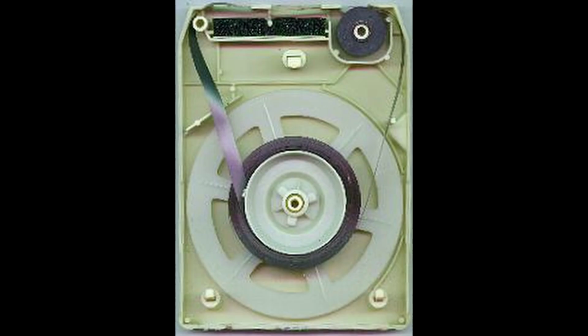But it pulls the tape from the center across the heads, and then each cartridge had its own internal pinch roller, so you could push this in from the front and it just mated with the capstan and was able to start pulling the tape through. So the only impetus to move the tape was actually the capstan and pinch roller, and pulling the tape off the center pulled the reel and pulled the used tape back onto the reel.